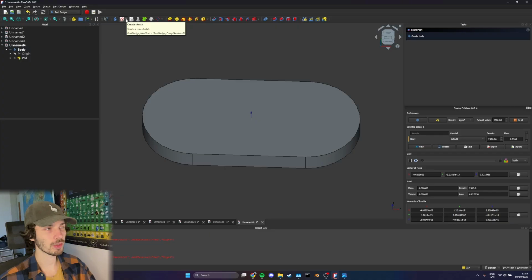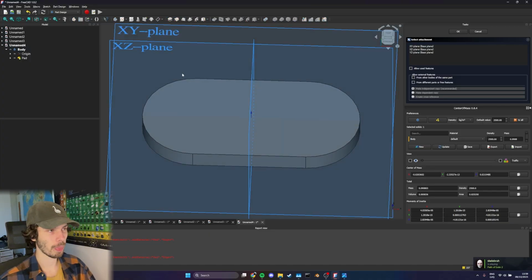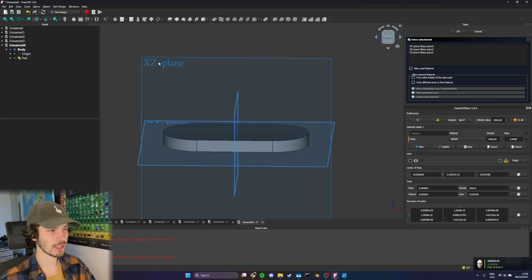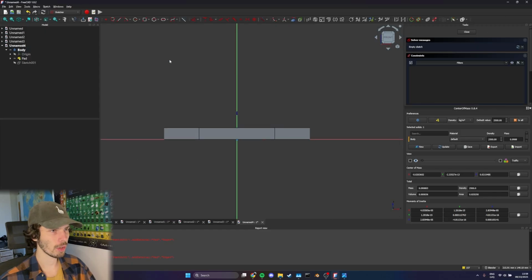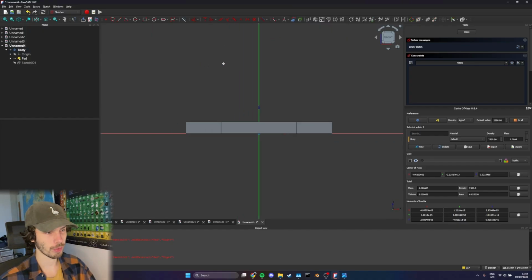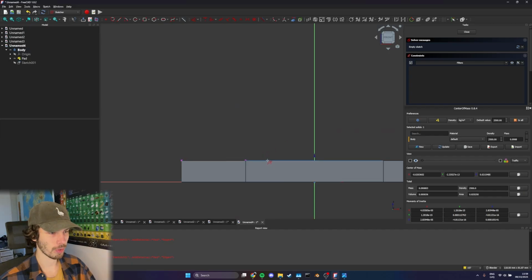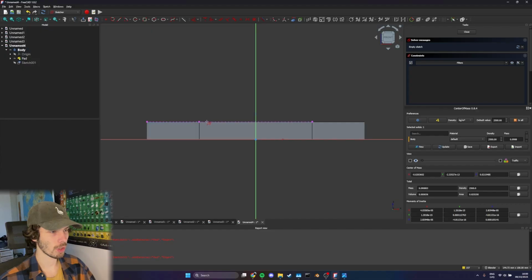After that is done, let's create another sketch for the pipe. For that, we'll be going into the XZ plane and adding external geometry. We can do that by finding this button, create external geometry, or with G and X. Let's import 2 of those points. If you can't see them, press the view section button and you should be able to see the imported lines over here through the geometry.